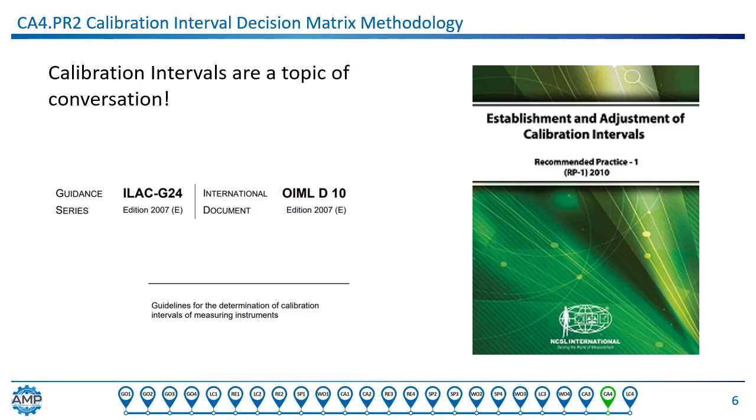These influences include things like the operating environment, such as hot or cold ambient temperature. Past shocks during transport or improper storage environments could influence the instrument's resistance to deterioration and hence the length of time it remains calibrated. Regardless, our certainty about the accuracy of an instrument begins to diminish as soon as a calibration is completed, and however long we can tolerate that uncertainty is the interval that we want to establish.